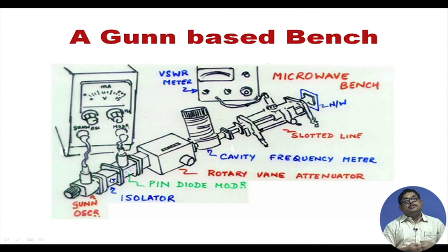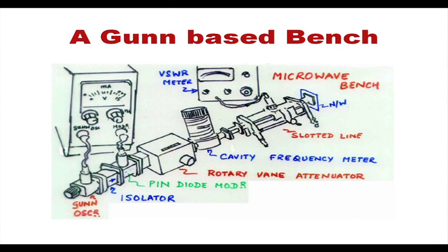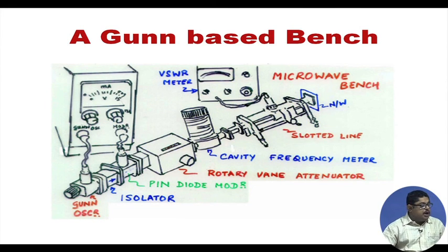That is why, for any oscillator circuit or any source that has a very small resistance, if a high voltage comes there, there will be a large current flowing through the source, and the source may get destroyed because its resistance is very small. So, that is why we put an isolator, so that the reflected power cannot come to the source, while going forward it passes.